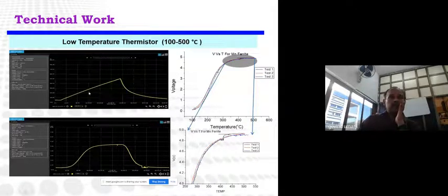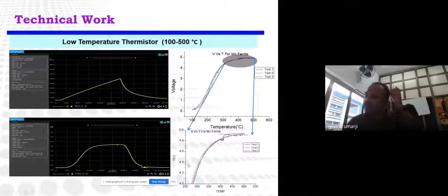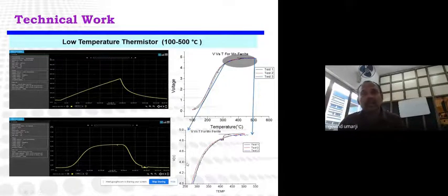The first graph shows there is a linear change in the temperature, and in this case the thermistor shows non-linear behavior. And from the device or prototype point of view, the value required is not in terms of resistance, but in terms of voltage, to give this data to any controller, Arduino, or program.